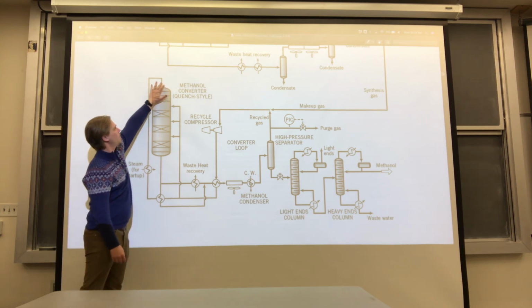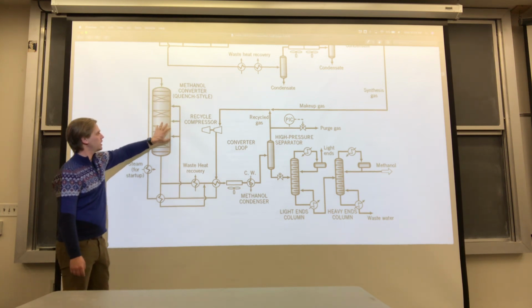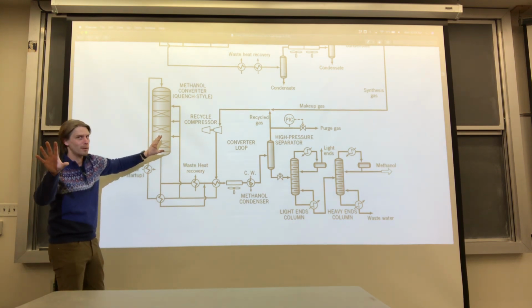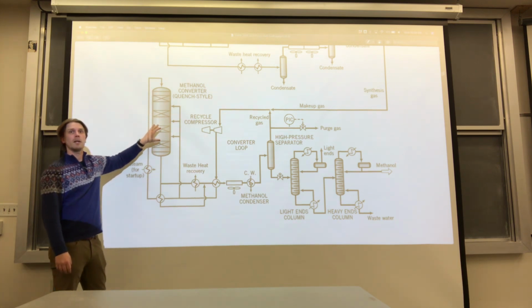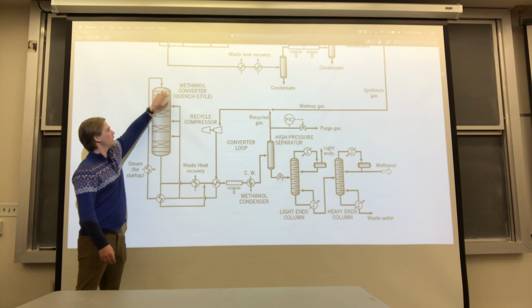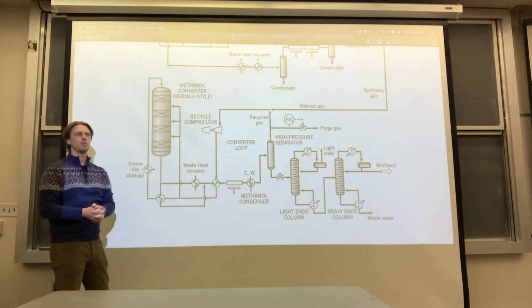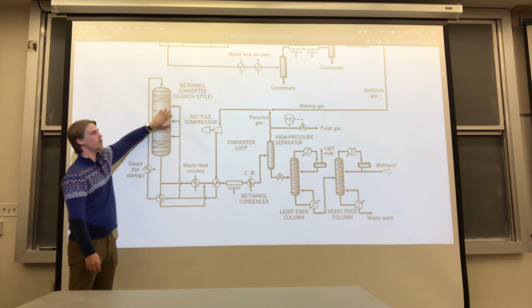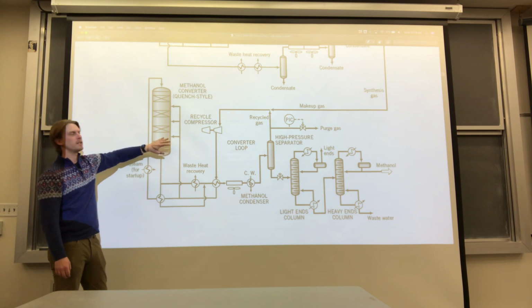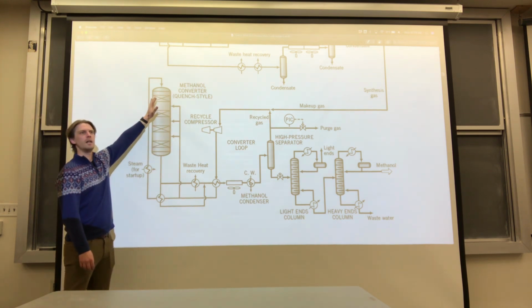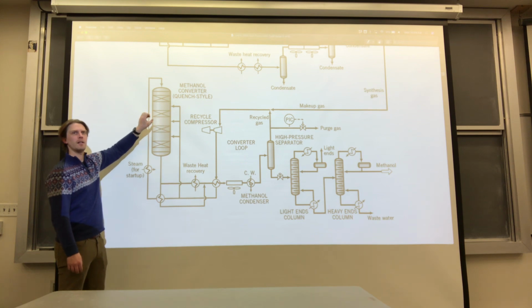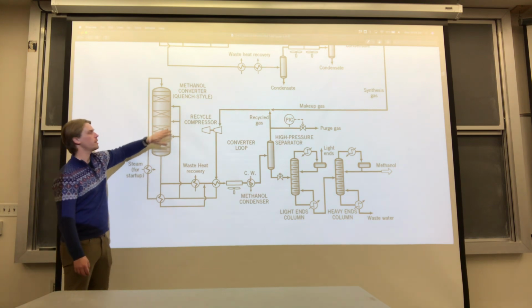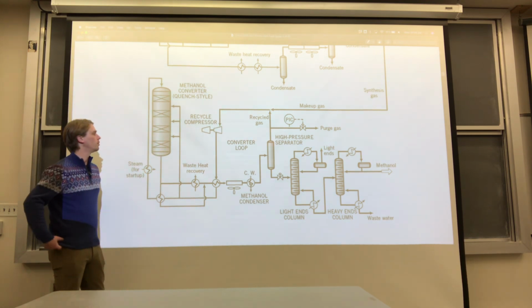Now, I guess we could say on this, in this process here, they're actually injecting the reactants in different locations inside the reactor. Again, this is a junior level problem. Don't have to worry about that. That's because it's exothermic. And by injecting into different locations, you get better energy distribution. Actually, I don't recall 100%, but I think it's exothermic. So you get a better sort of energy distribution so you don't get hot spots. Because catalysts, right, they're sensitive. If they get too hot, they can deactivate and then they become not as useful, right? So these all have catalysts in there to help speed up the reaction. So controlling the temperature distribution inside of a reactor is going to be important.